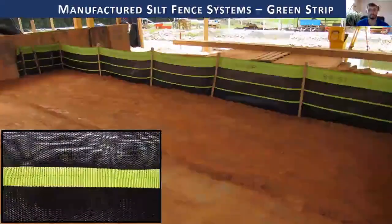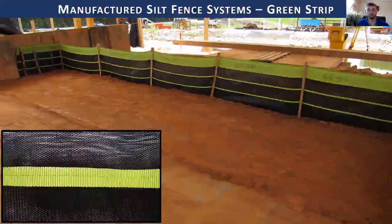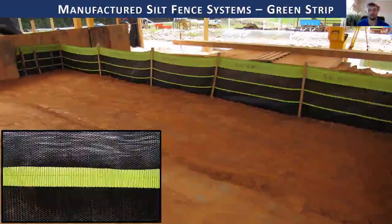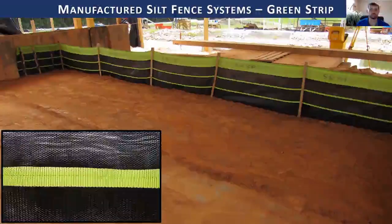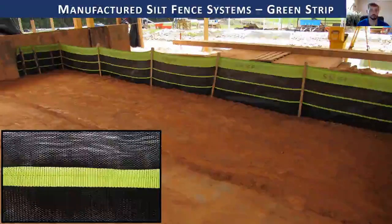We also looked at the green stripe manufactured silt fence system. This is a very similar setup, except the geotextile has woven belts, the green stripes, that are considered the reinforcing strips. So instead of having a polypropylene netting backing, we have built-in reinforcing in the geotextile.